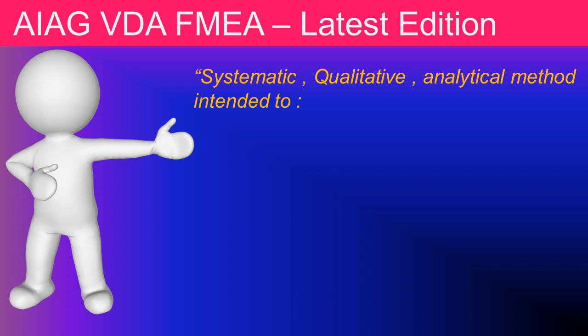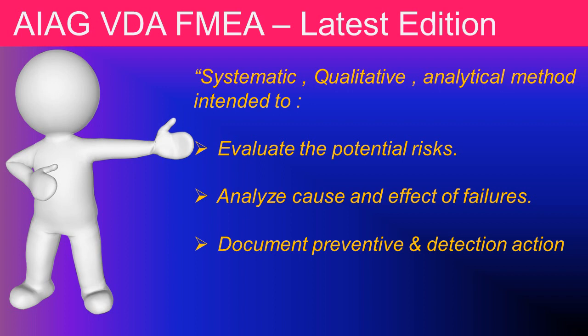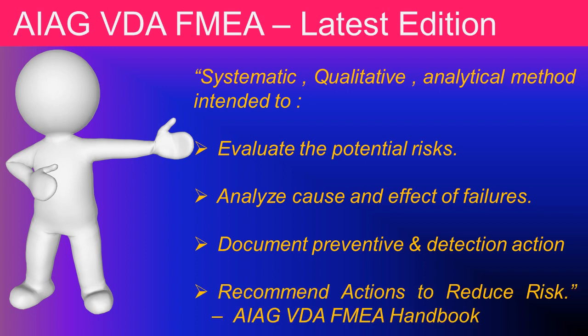As per AIAG VDA FMEA, it defines FMEA as a systematic, qualitative, analytical method which is intended to evaluate the potential risk, analyze the cause and effect of failures, and document preventive and detection actions and recommended actions to reduce risk.